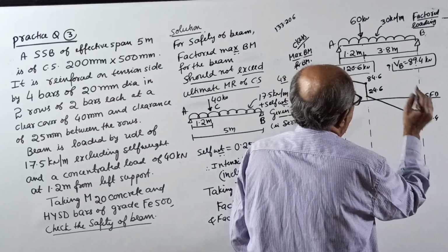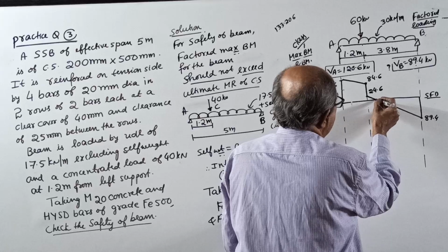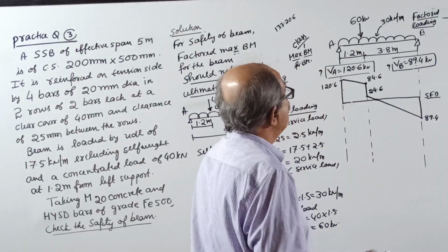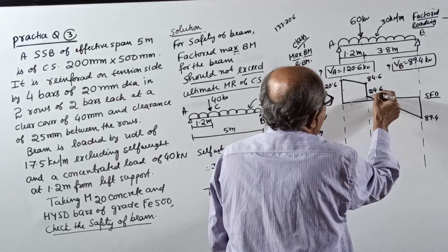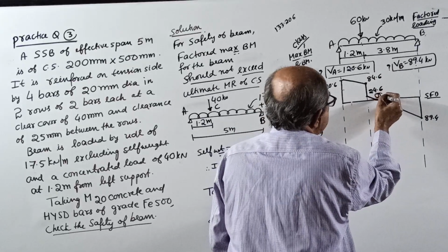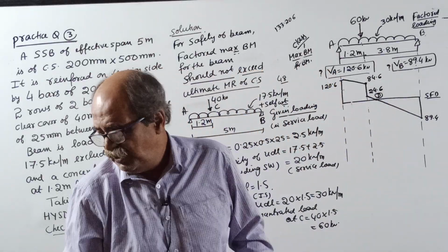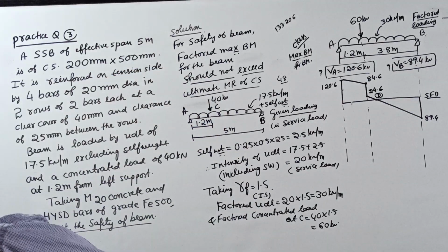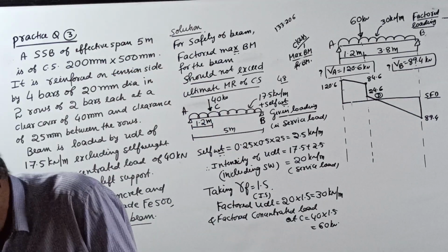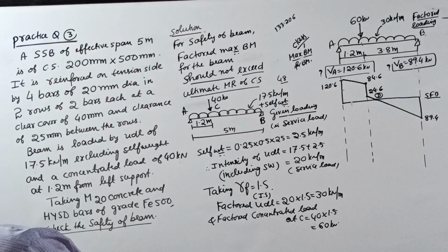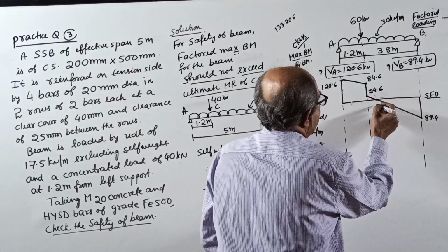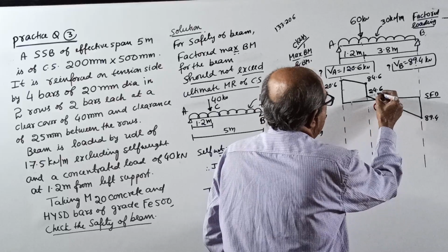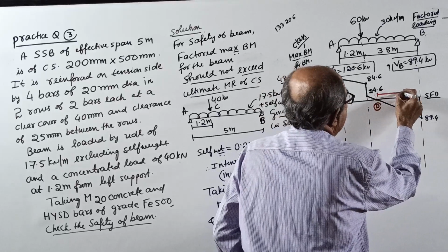Go up, over. This is the point where the shearing force diagram crosses the baseline A, B, C. I will call this point D, a special point. I use red color to understand. Actually, red color is not required. Still, to understand, red color. Okay. It is an important point, D. Let it be X from here.